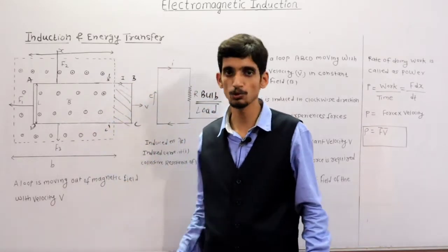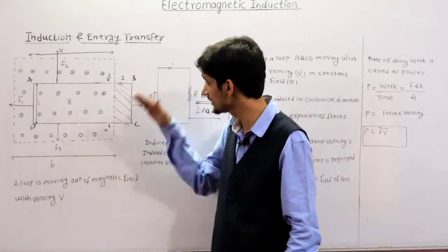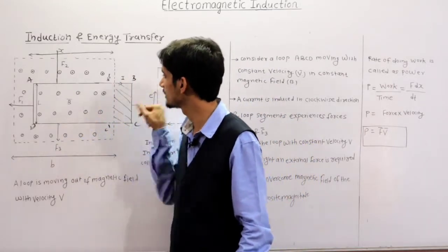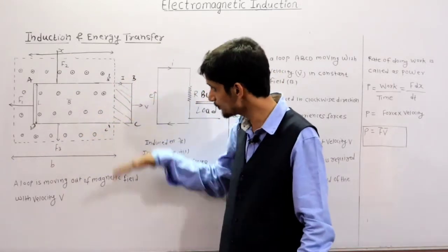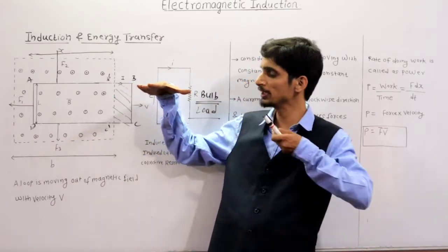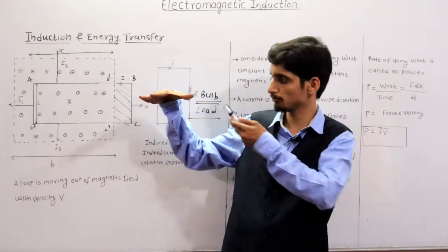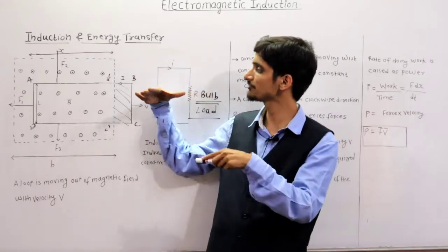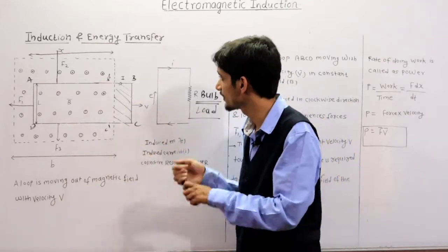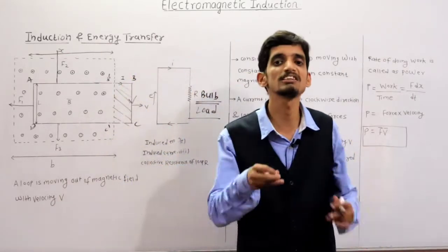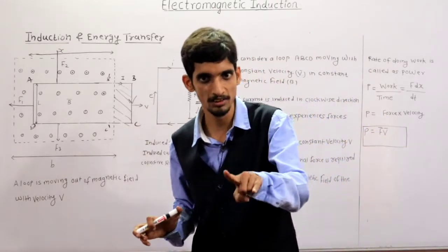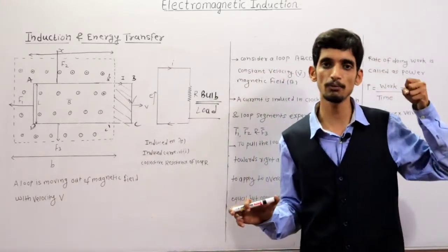Charge accumulated. So due to this, positive charge is accumulated in this particular segment and negative in this one. So current will flow like this. That's why the current direction is like this. Current is downward. Because in this condition the thumb is pointing towards me, it means I am pulling that segment towards me. Then the fingers indicate the field out of the board, and this palm indicates the current, which is downward. So it is an easy way to mark the direction of current. There is no necessity to mug up the things. Clear? Okay. So when we pull the segment, EMF is induced.